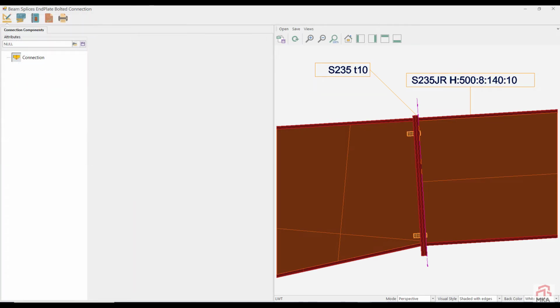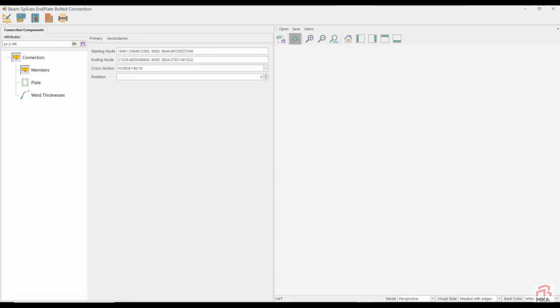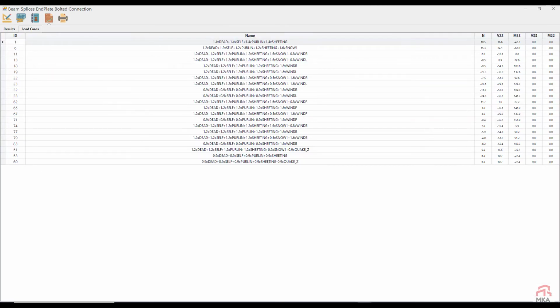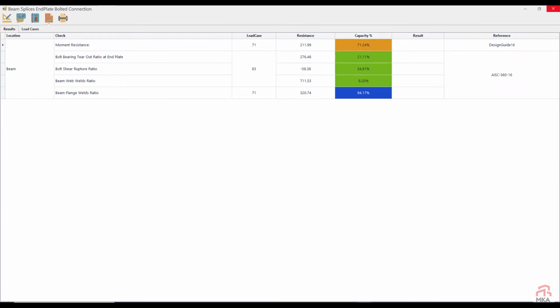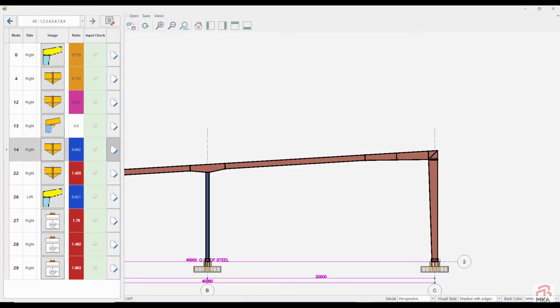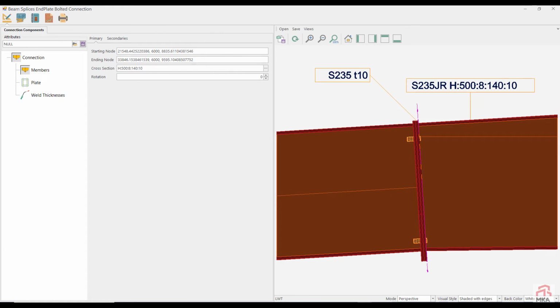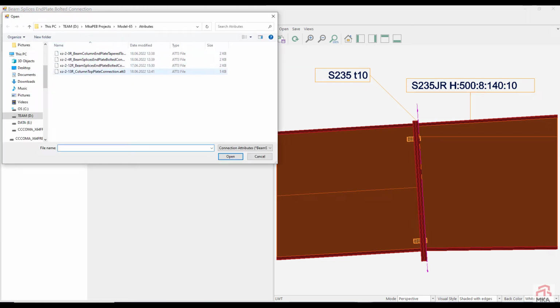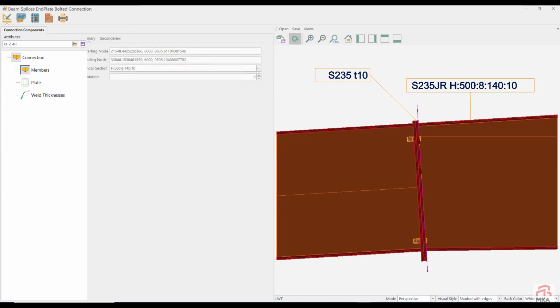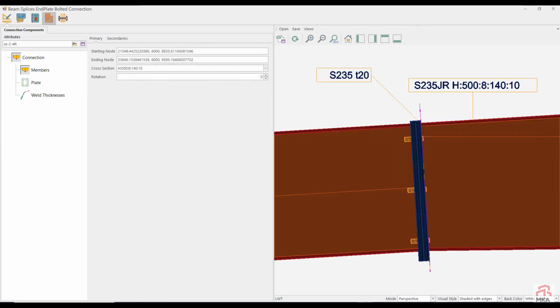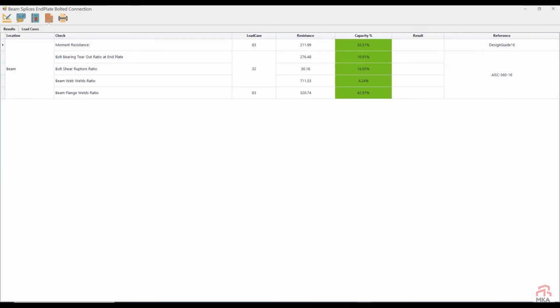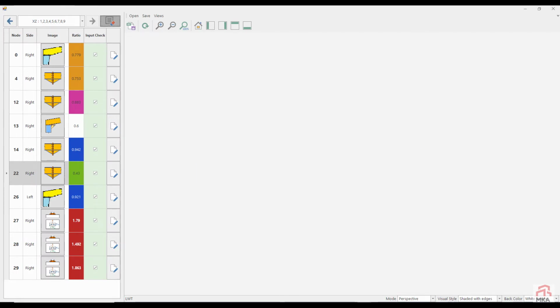We're on other splices now. The 4R was our splice, the one with 3 bolts. Let's look at the results. Weld thicknesses are within limits. Of course, we should not stay within such limits. Could it have been done better? It would be better if we increased the weld thickness a little bit. This is how we completed our connections.